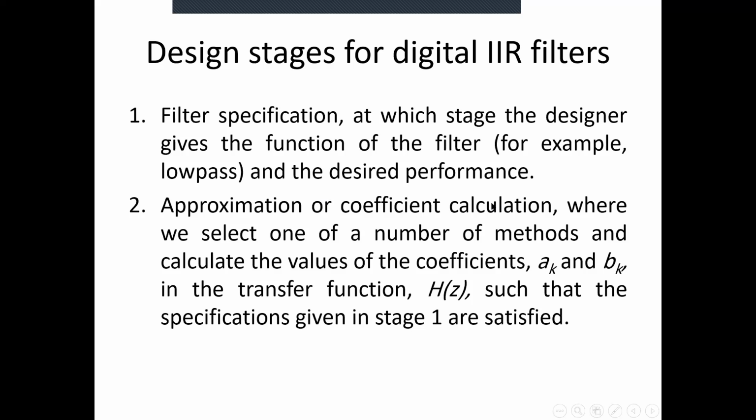Of course, to find out the filter coefficients in the IIR filter, we have techniques. First technique we said will be the pole zero placement. Second, impulse invariant, and the third one will be bilinear Z transformation. Now, in FIR filter, we have H coefficients. I mean, H0, H1, H2, H3, H4, H5, and so on, up to say, for example, H50 and so on.